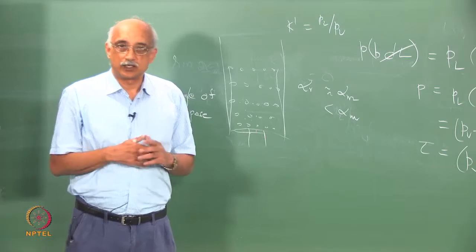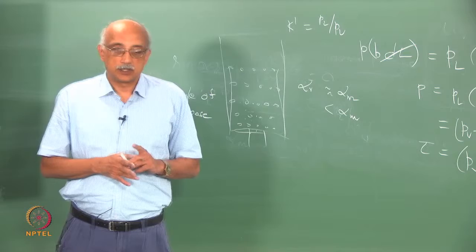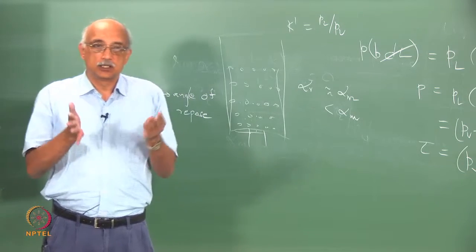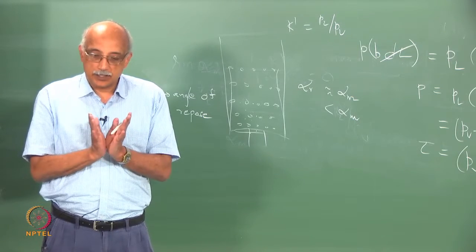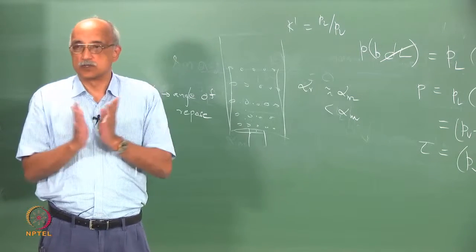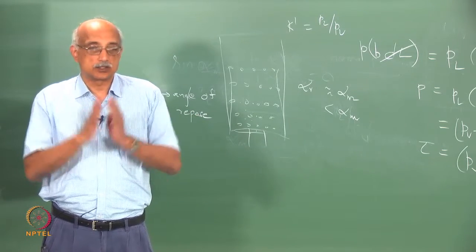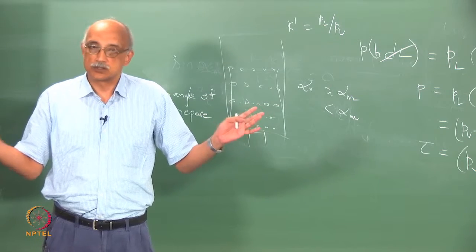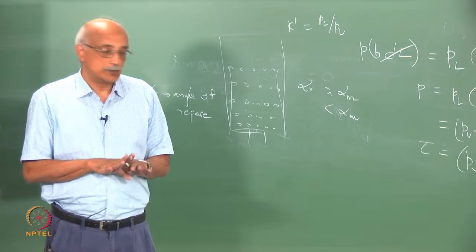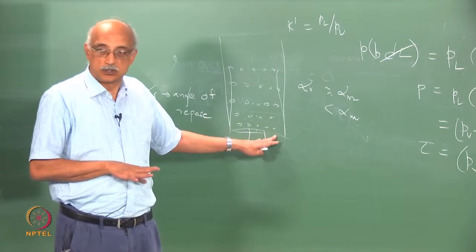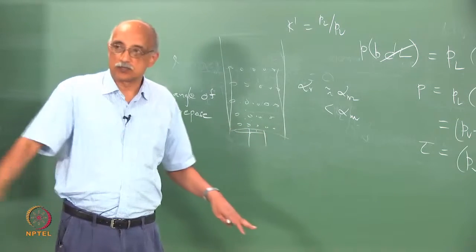I do not know if you have had any experience where you store things, open up and see how the material flows, but the initial flow of material will be the column of material that is right on top of the opening. Slowly it will take a funnel-like form, it will slowly start expanding, and after a certain point the particles that are near the walls will start discharging, and the last piece of material to discharge will be the material that is already on the floor. It has to eventually migrate to where the opening is and start flowing out.